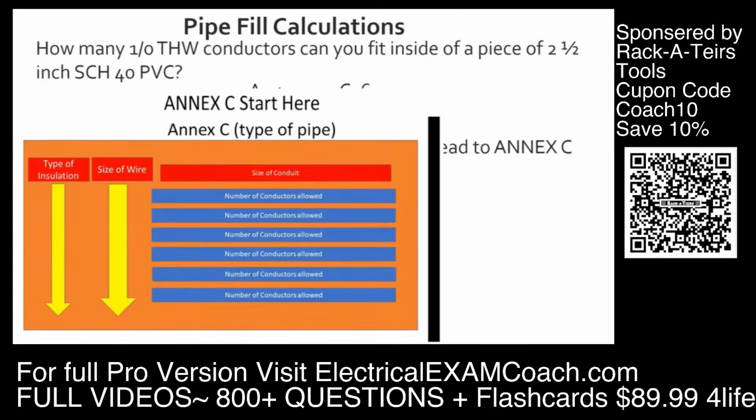When we find it, we go to our size of wire, come across the top until we find our conduit size. Then we're going to come down and tee off and find that we can fit 8 more conductors inside of this conduit. Great job.